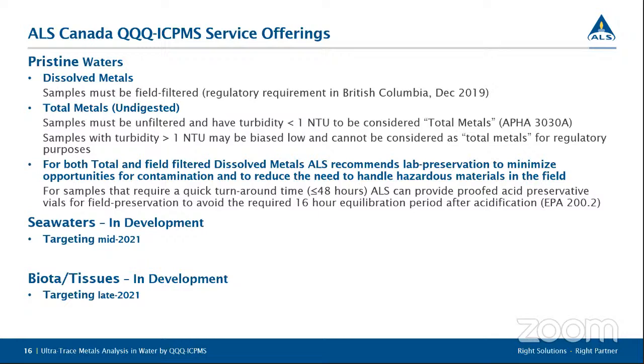For dissolved metals, samples should be field filtered through a 0.45 micron membrane filter and sent to the lab unpreserved. Field filtration became a requirement for all regulatory work in BC in 2019. It is highly recommended that a field blank is also submitted to aid data interpretation.